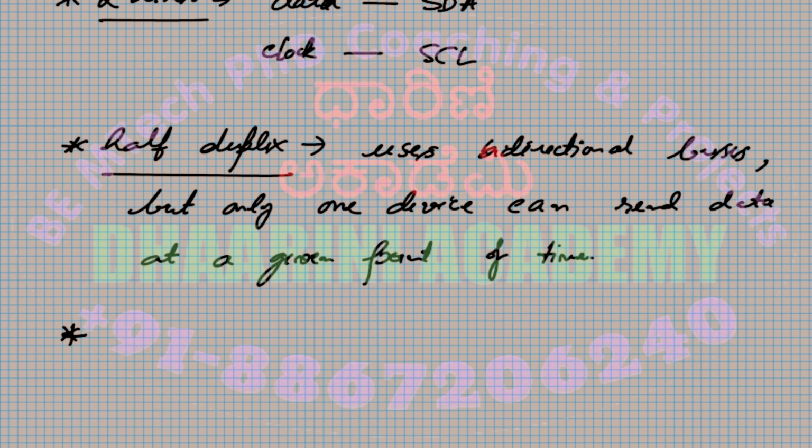You may have an ADC, DAC, right? Look at the various blocks present over there. For every block you need to generate a control signal saying yes, now you do the write. Yes, now you do the read. Yes, now you add. Now you put your result onto this bus so that it goes to this address. You see, so many things are there, so you need a complete block for generating the control.